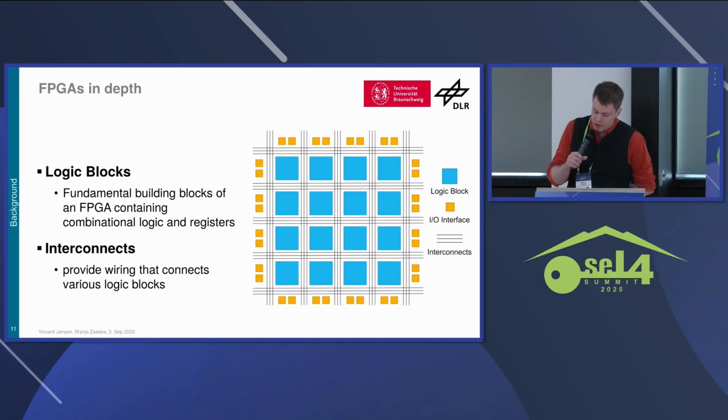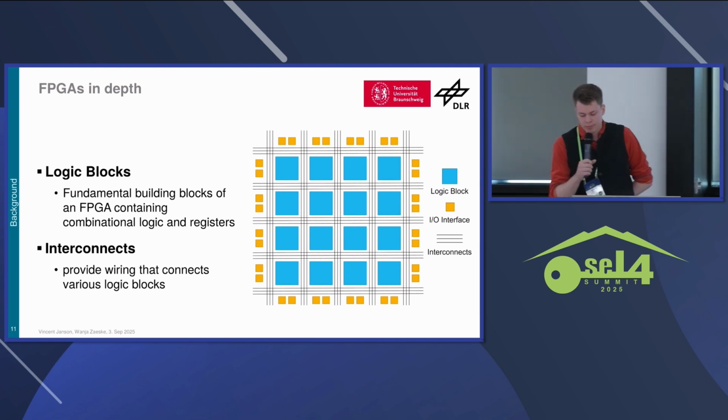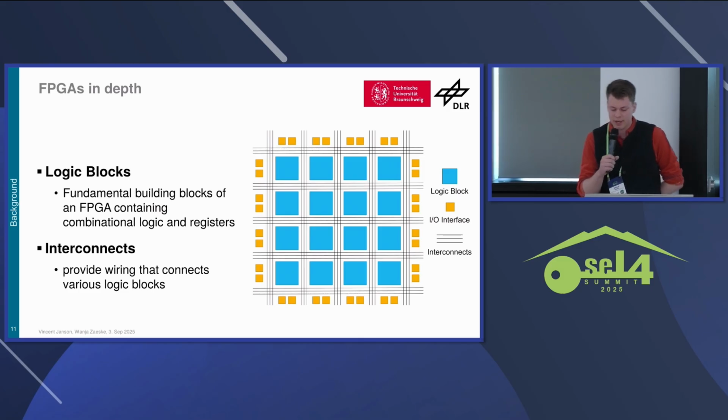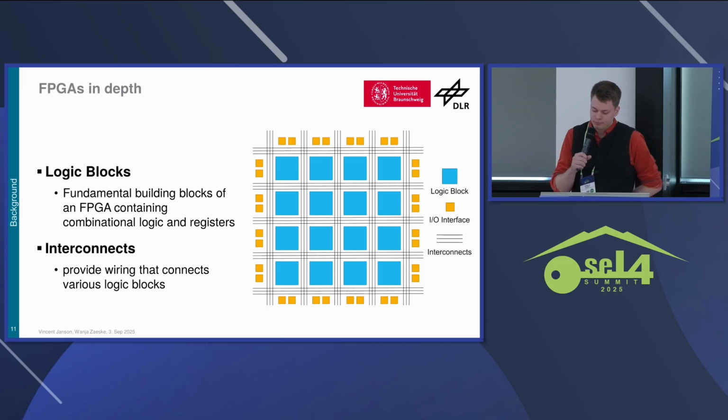Now, how does the FPGA generally work? So the pattern that seems to be prevalent in current designs is that we have an array of logic cells, and these logic cells are connected via interconnects. And you can basically program any kind of logic function inside of these logic cells, but you are constrained with the number of inputs and outputs.